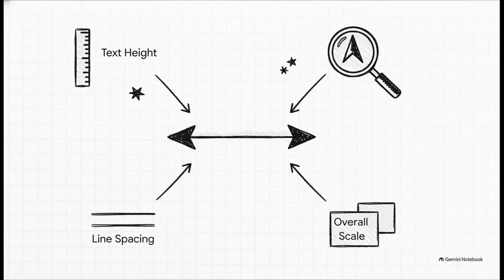This brilliantly illustrates the sheer power you have from this one single menu. Within those tabs, you're dictating the exact text height, font, and placement for your numbers. You're defining the arrow size, the arrowhead type, the leader styles. You completely control the granular geometry of the dimension itself: line thickness, spacing, extension line offsets. You dictate the units and precision, literally telling the software exactly how many decimal places to show. And crucially, you set the overall scale factor.